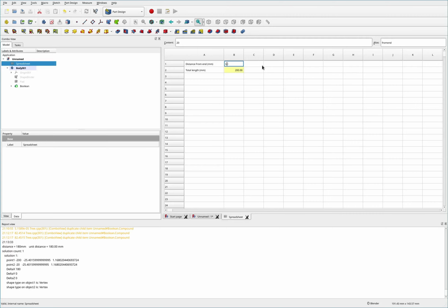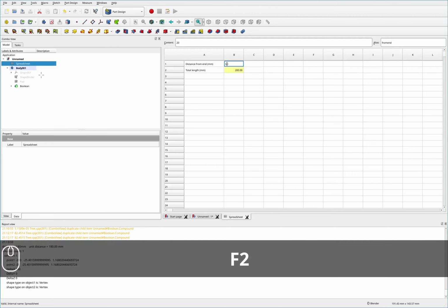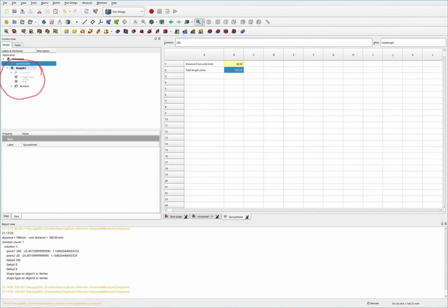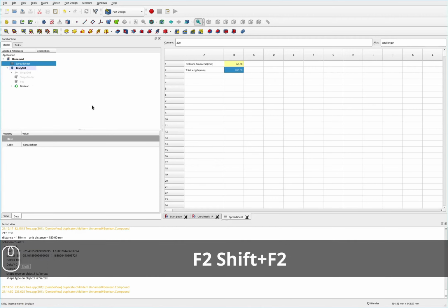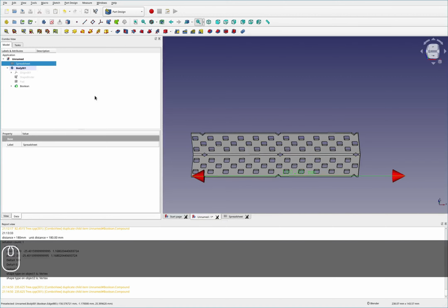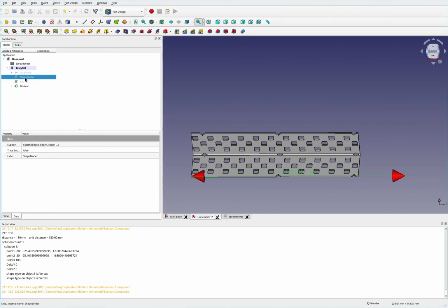If you are using a version of FreeCAD with the topological naming problem, I would recommend that when you go to do any type of mates, or any type of mating two things together in one of the assembly managers, that you actually mate to the original shape binder here.